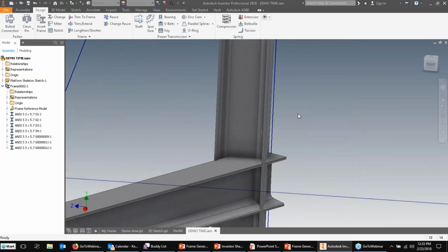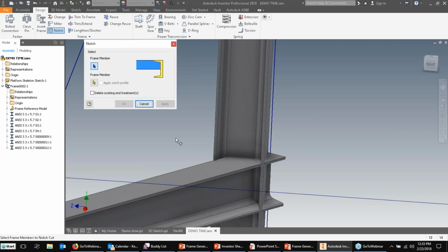Now, this is what I was referring to that Revit Structure does automatically. With Revit Structure, you run a cope, and it will automatically cope and then ask for mechanisms on how to secure this connection. With Inventor, it keeps everything small. They're assuming you're going to weld pretty much everything in here. That's what we're doing with machine framing. We're welding 99% of it. So you're not prompted with any kind of bolted connection or fastener connection or reinforcement connection.